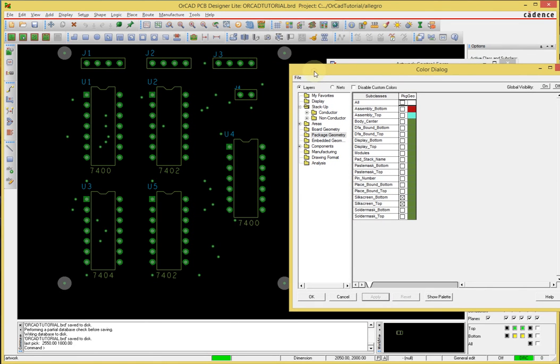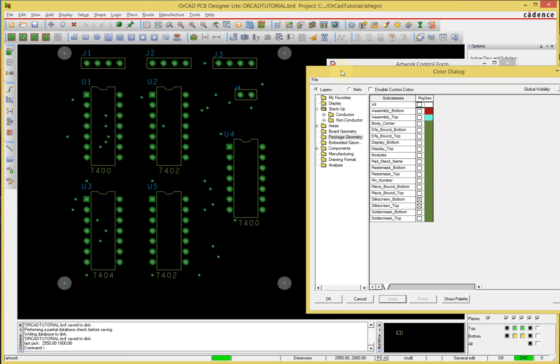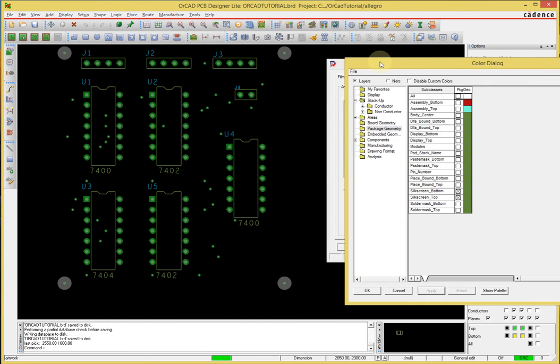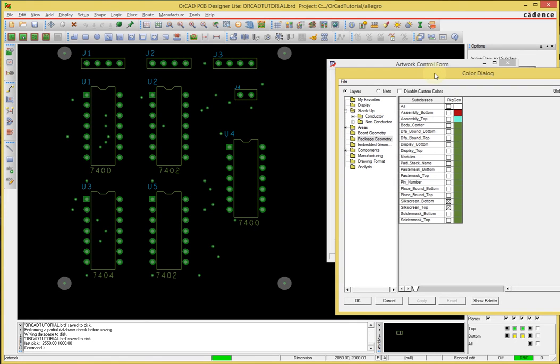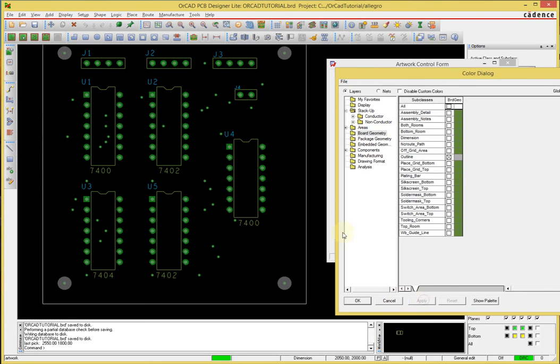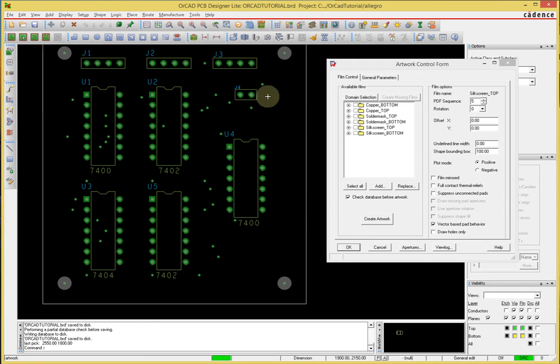We need a board outline actually, and I forgot to do that in the other video. Let's go back. It means our board is actually not complete. Or let me see. I think that we can do a board outline. Package geometry outline. Apply. That's my board outline. Okay, so I can click OK.